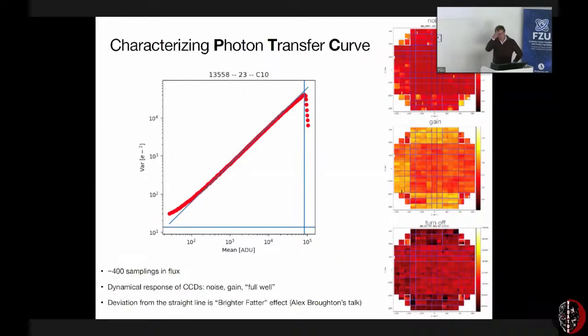So that's a photon transfer curve. It's a standard way to measure performance of the CCD when you send a signal and accumulate n photons in a pixel. Then this n fluctuates Poissonically, as a square root of n. So you can relate the variance, the square of the variation, and the signal should be linear, with slope one, if you express everything in number of electrons.